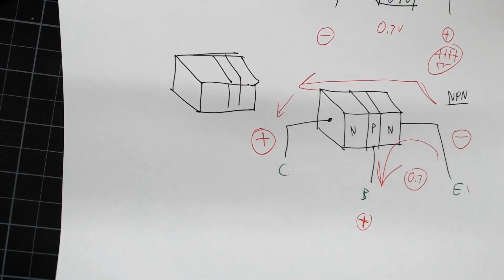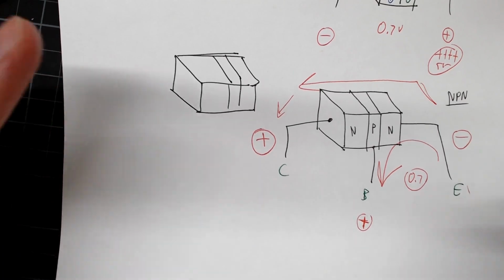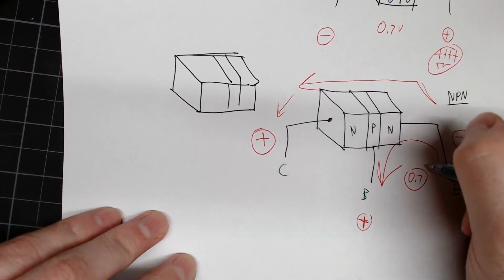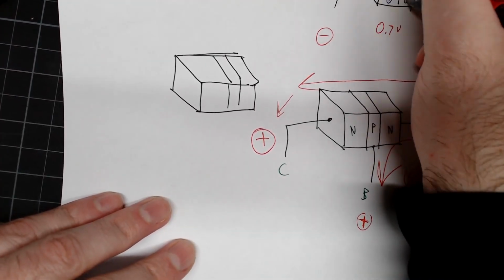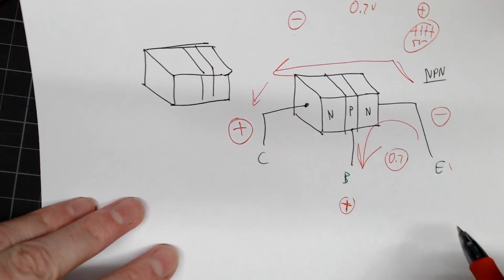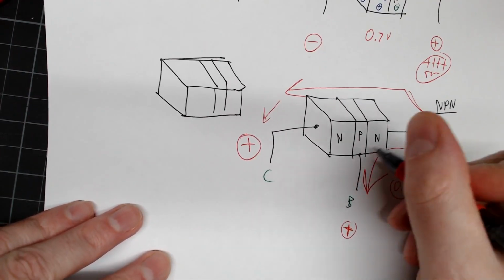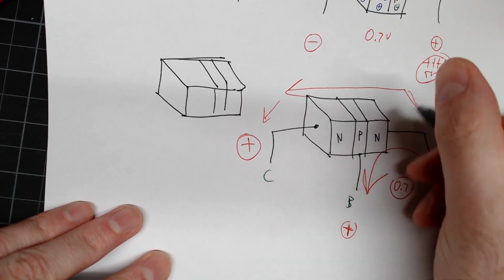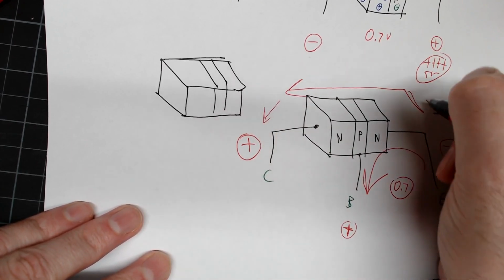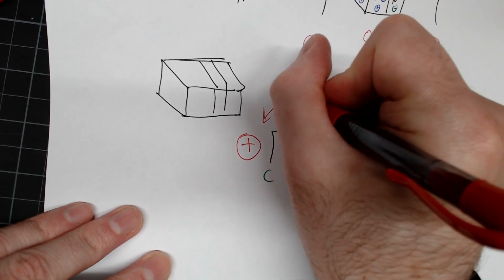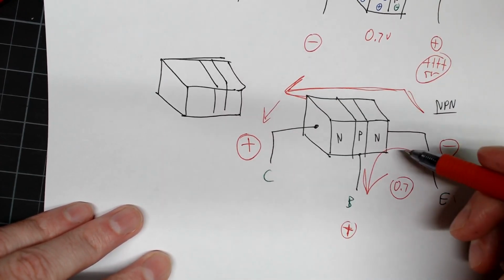It's going to depend. Our transistor, I looked up the data sheet, is, I think it was about a volt. It might have been, I'd have to look it up again. I think it's about a volt, somewhere between 0.7 and 1.2, and I think it's going to depend, but it's a small value. It's the same idea. It has to push through this wall, this junction. Once that happens, it primes the way for this guy to allow current to flow through here.